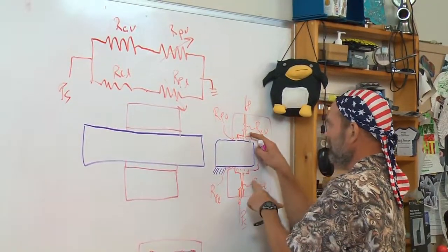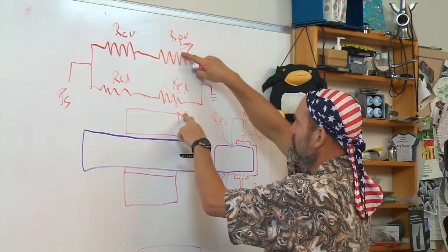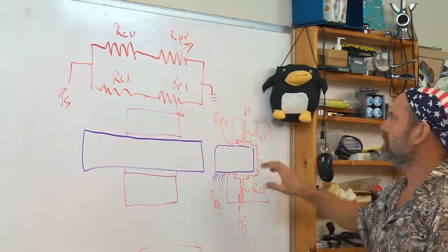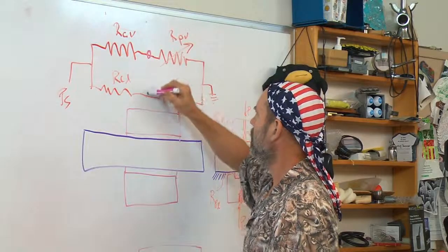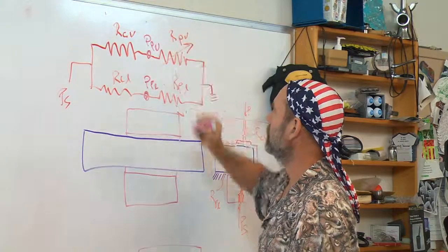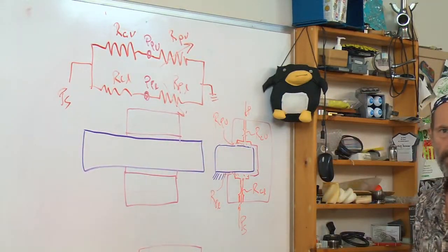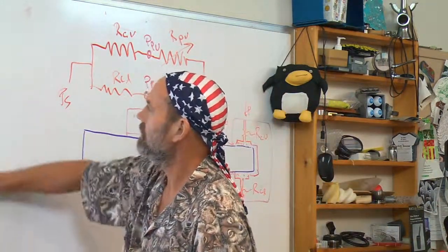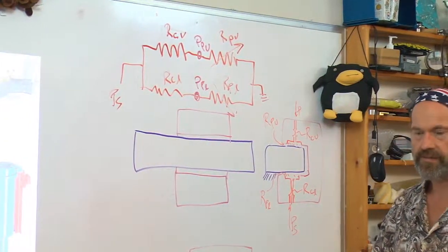These two compensation resistances are equal. One goes higher, one goes lower, or one goes higher and one goes lower as this moves up and down. The pressure inside the pocket, pressure pocket lower, pressure pocket upper, depends upon the ratio of the resistances. You can read the detailed math in the text. Suffice to say, it works great.